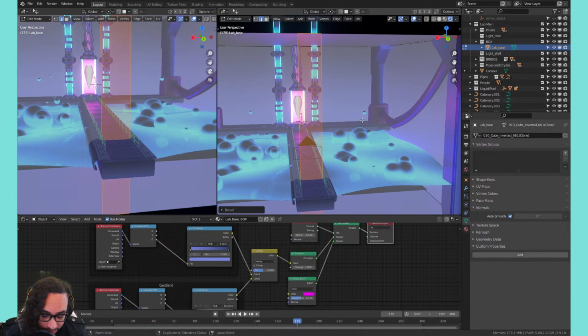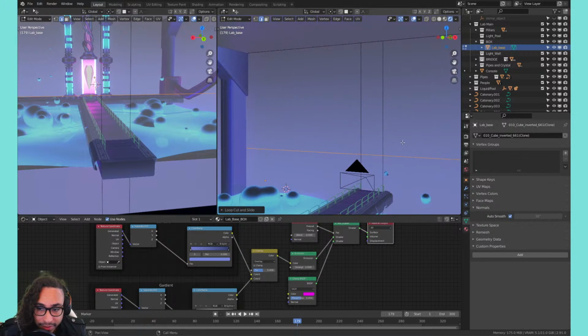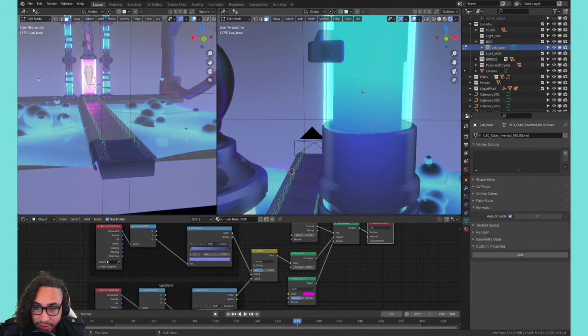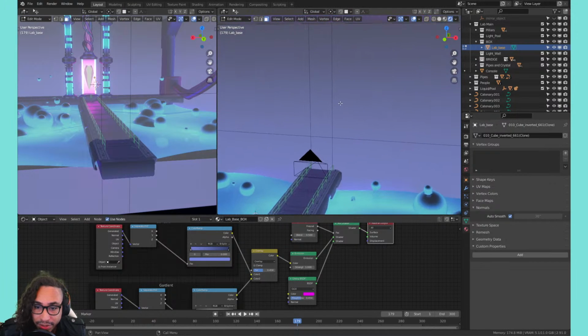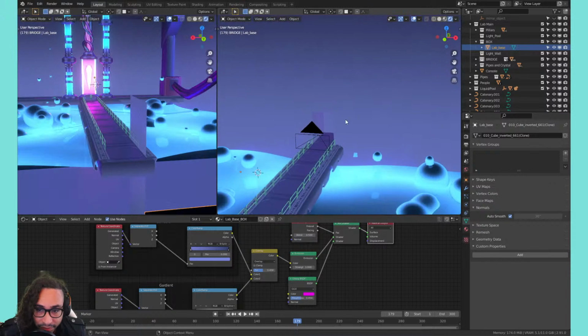And this door's going to be huge. So we'll cut it in half again. And I know it's hard to see, but I'm just cutting up the plane, right? Because now I have this wall that's broken up into a bunch of bigger squares, and I can select this wall and then extrude it, and then it becomes a hallway, which works out for me.